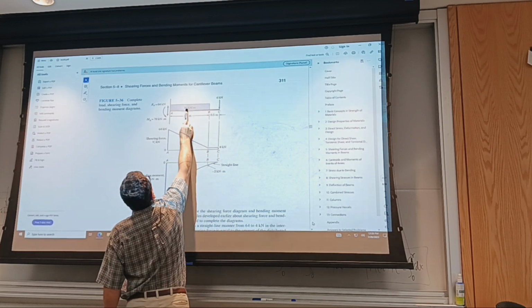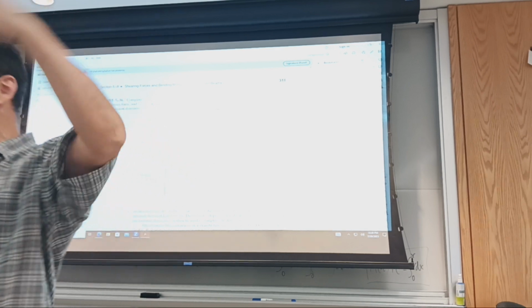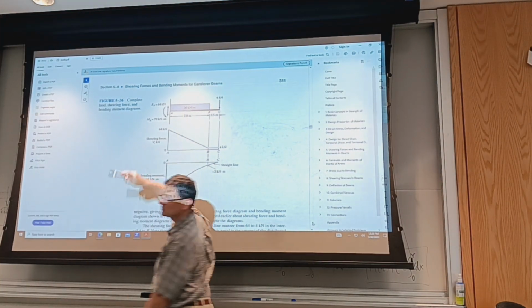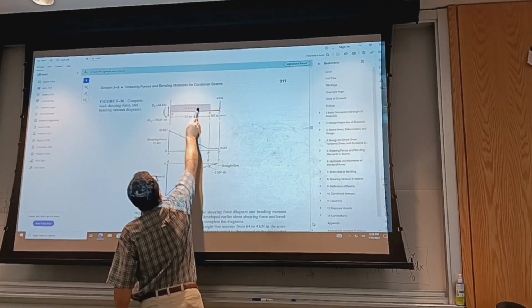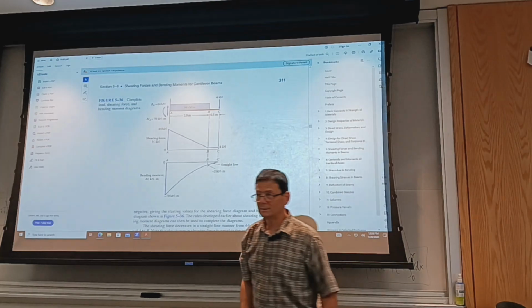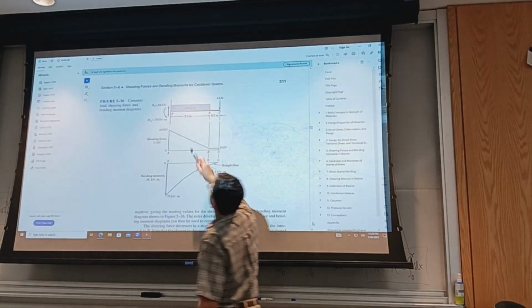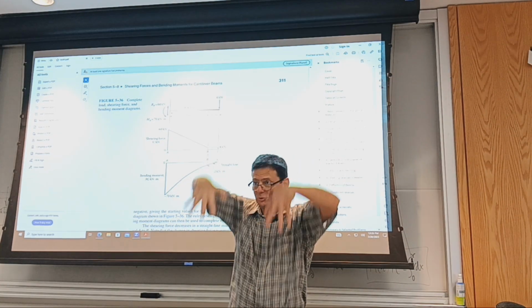drop. Again, because most of the distributed loads come from above and they are due to weight, they never say this is negative 30 kilonewtons, but it's negative to us, okay? Because this is a negative slope and it should match this value if it's linear. Does it make sense? Do you understand what I'm saying? So even if it shows on the diagram at 30 kilonewtons, if it's above, it's assumed that it goes down.